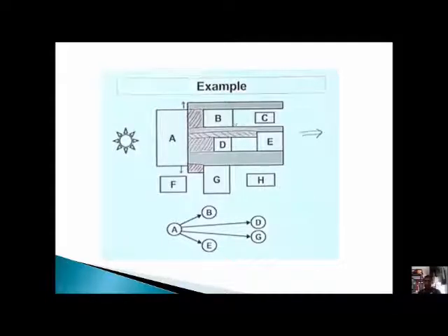If we want to check C, we have to remove this B and check how far the shadow is propagating to C, and what the gap is between A and C. From A to G it is also diagonal, so here also we can have the shadow, and we can know how much distance there is from A to G, and therefore we can reduce the space. We can move G up to whatever the constraint is, 3 lambda or 2 lambda. We can move up to that.